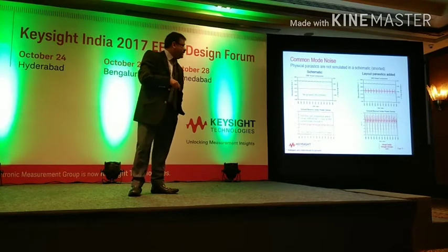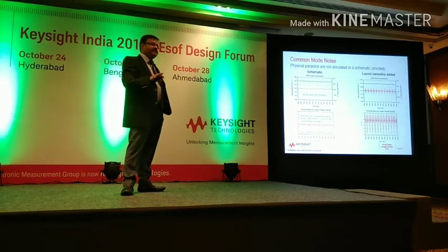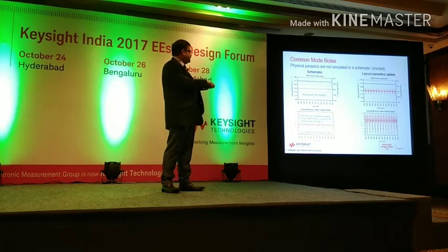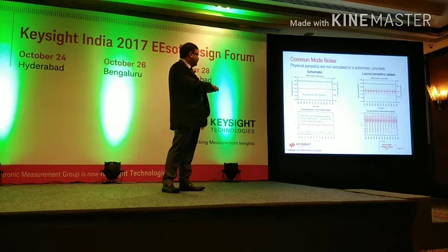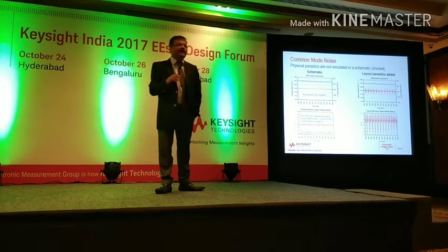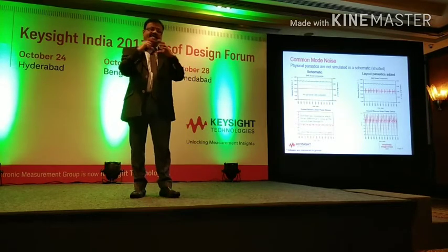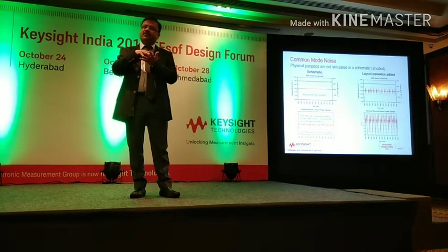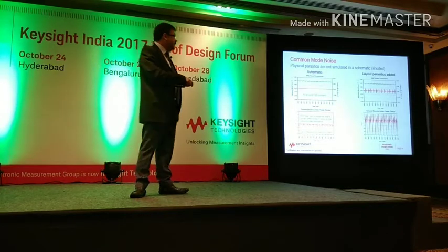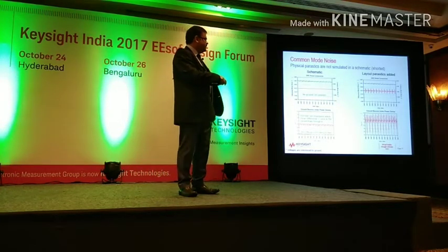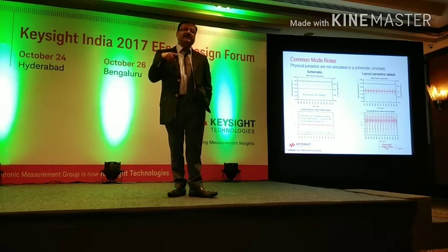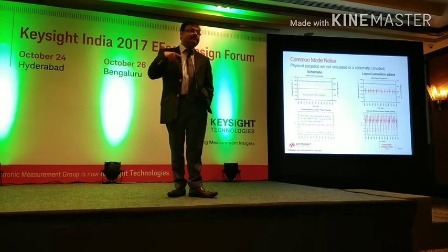Okay, now here is what happens in real life. You set up your circuit, you simulate your power converter circuit, you look at the schematic response, look at the noise response, everything is beautiful. No ground common mode currents. Little ground spiking is seen at the schematic level. So your schematic doesn't produce any so-called EMI kind of effects. You go ahead and fabricate your PCB, you populate your PCB, assemble everything, and you test. And that's what you end up seeing. You see these huge spikes coming up in your power converters.